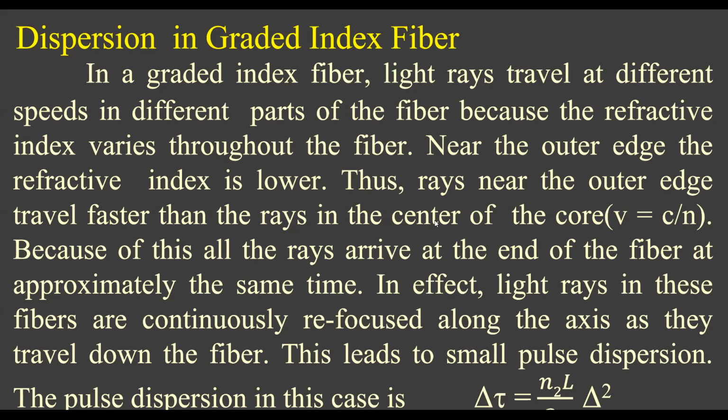Welcome back to our topic of fiber optics. In the last session, I was discussing dispersion in optical fibers. I discussed the dispersion phenomenon in the step index multimode fiber. Now I am discussing this dispersion effect in the graded index fiber.